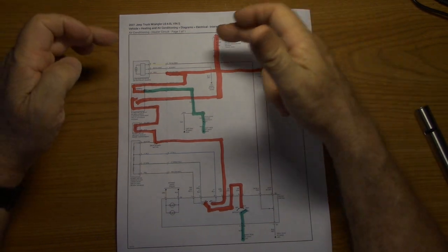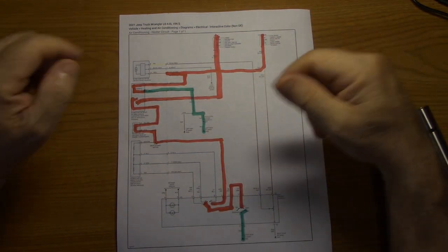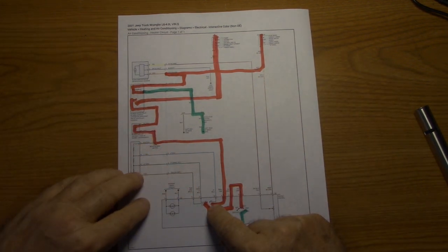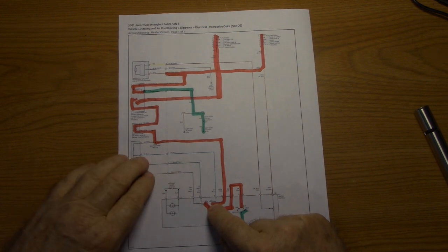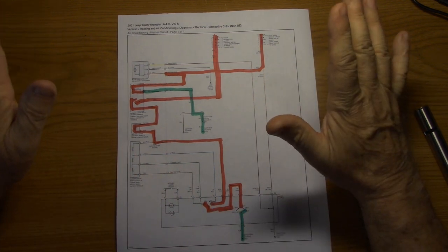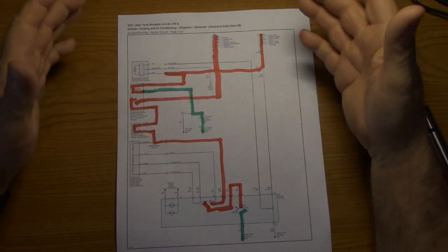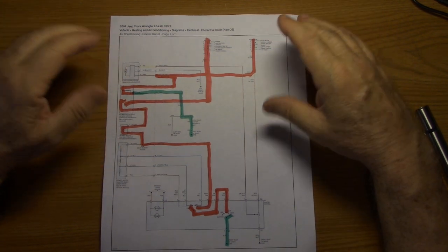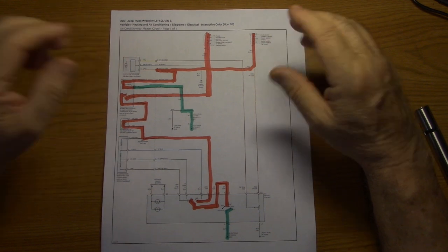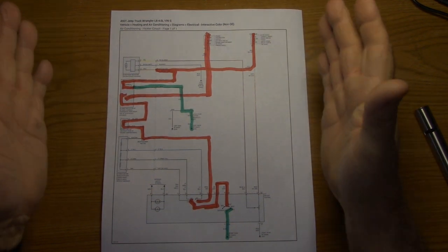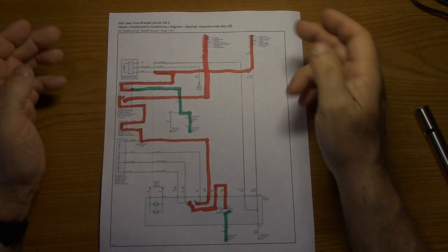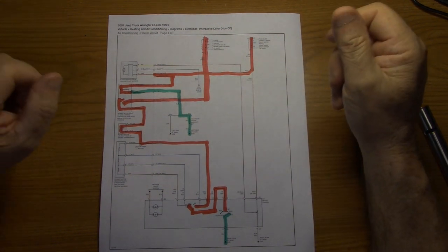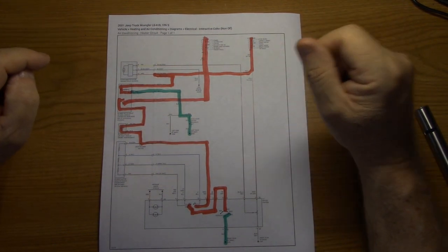But I want to make sure that I have a good circuit with a blower motor that works. And testing in high, you can eliminate all of this. You don't have to worry about the ballast resistor, so try and make it as simple as you can. So we'll go out to the Jeep, and I'll walk you through. Maybe it'll make a little more sense when you see me doing it, because I'm not that great at explaining it. So in a nutshell, we have 2 circuits we need to troubleshoot, and we're going to start at the fuse and work our way through the circuits using this diagram and find out where our problem is. So I'll see you out at the truck.